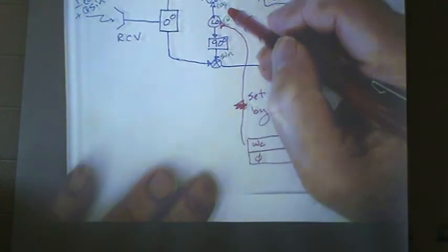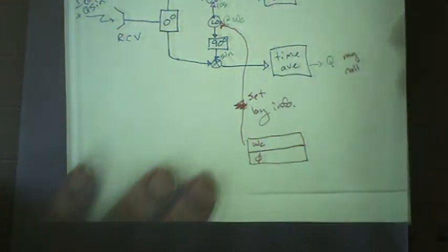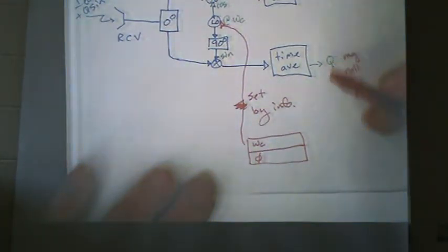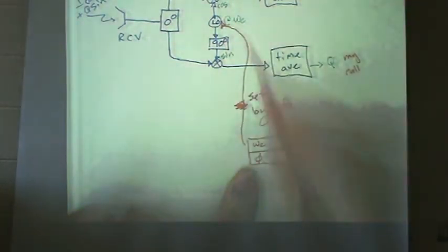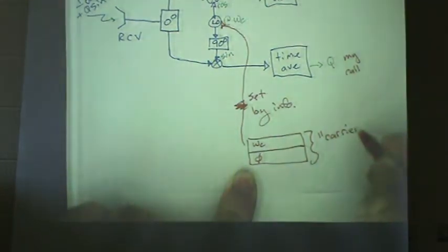The other is, well, if that's not cosine, if that turns into sine, then instead of giving you your phone call, I just gave you my phone call. Right? I'm going to mix I and Q, or you get half of one, half of the other, or some other mixture. So it can only work if I can tell this local oscillator what the phase is compared to what it was at the transmitter. Right? This is called a carrier recovery circuit. It's complicated.